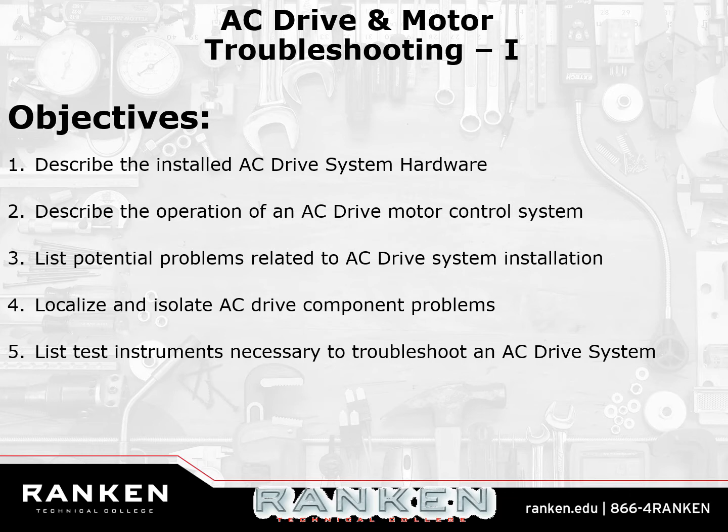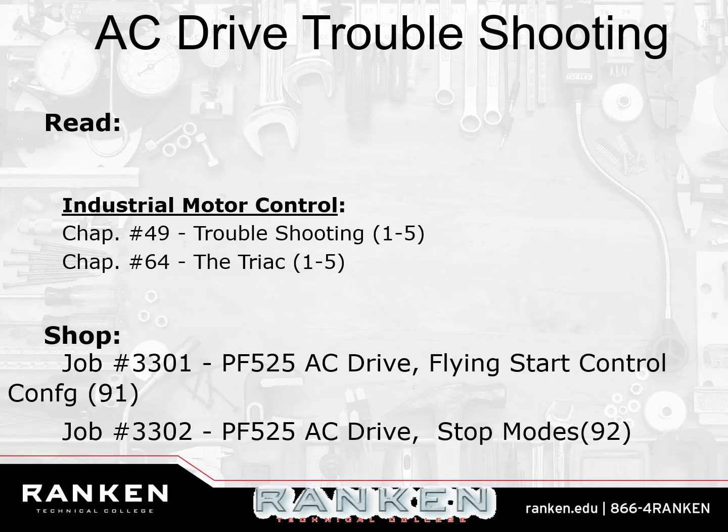Like I said, my rule of thumb, or the way that I was always taught, is that you really don't do a lot of troubleshooting with drives that are less than 100 horsepower. You just throw them in the trash. You might have to figure out if it's the motor or the drive, which is pretty simple. If you unhook the motor and you let the drive run and the drive still trips out, then it's the drive. If you unhook the motor and the drive doesn't trip out, it's probably not the drive. It's pretty self-explanatory.